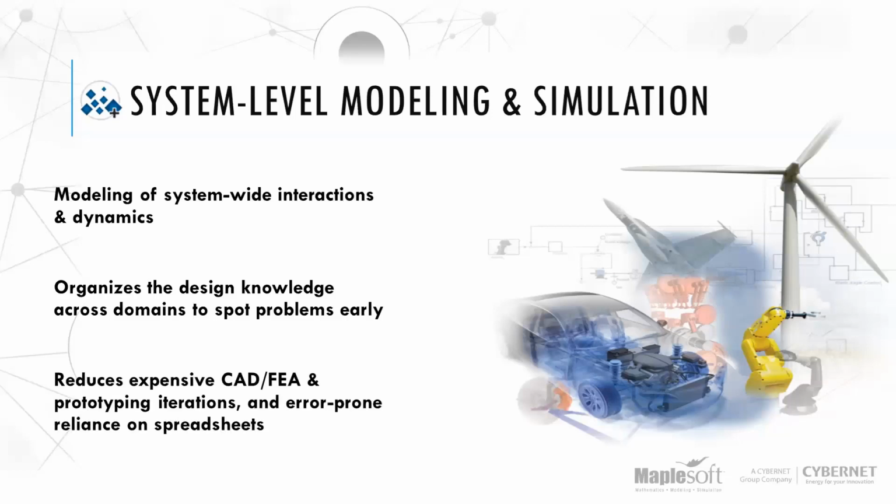And it also helps reduce the cost of other kinds of prototyping iterations, CAD and FEA iterations. Let's say, for example, in this tool, we have a heat transfer library. You can model on a high level how heat is moving around and then narrow in your design space before you need to really unleash days or weeks, at least, of heat transfer analysis in FEA. So it helps get you to the prototyping stage sooner and more reliably.